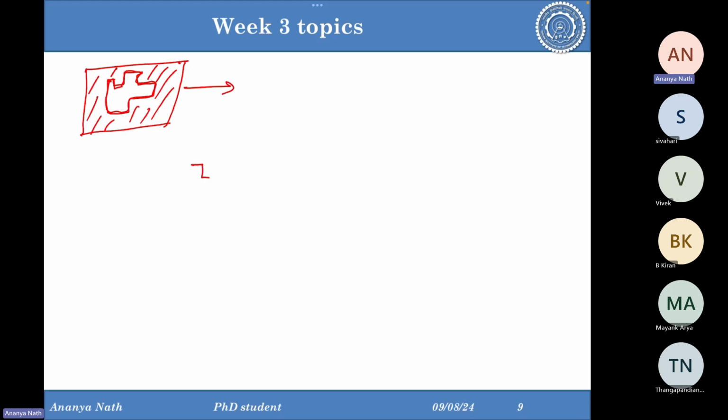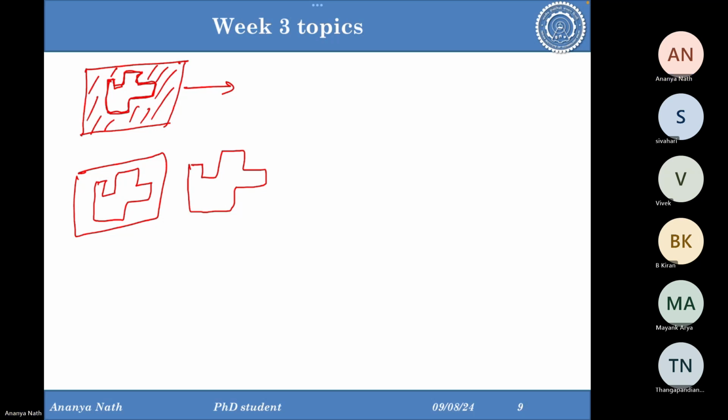Okay, and we now have this object. Again, another sheet will come and the laser again will cut the object like this and it will fall over this sheet exactly, and everything will get glued to each other with a little bit of heat and roller pressing. So here, grid by grid.